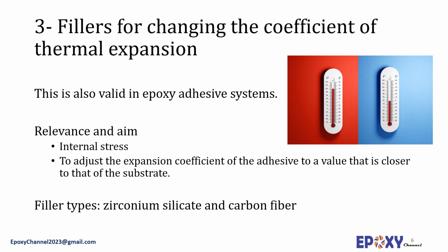When a liquid adhesive solidifies, the theoretical strength of the joint is reduced because of internal stresses and stress concentration that usually develop. These stresses occur when the joint is taken to a temperature that is different from the curing temperature or when it is exposed to thermal cycling. The most common cause of internal stresses is the difference in thermal expansion coefficient of the adhesives and the adherents. Using a resilient adhesive that deforms with the substrate during the temperature change is a possible solution to